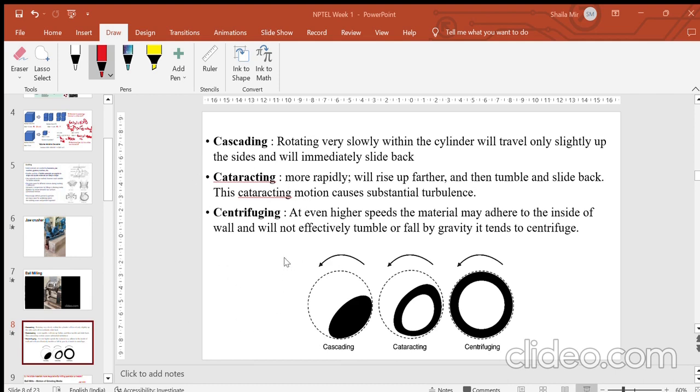That means the balls and the charge rise here, and then fall at a point which is called the toe, and the major grinding happens in this region, while there is no grinding in between. The major grinding only occurs along the edges and along the path at which it drops near the toe. So you need to identify that for a ball mill you have to keep it not completely filled, because you have to achieve this open area for milling. You have to have some free space inside the mill for crushing purposes.